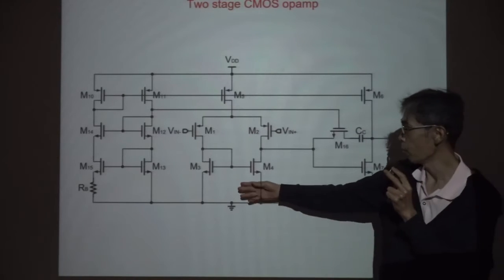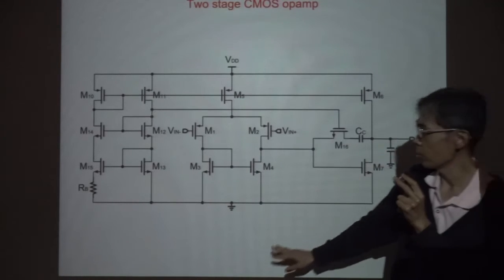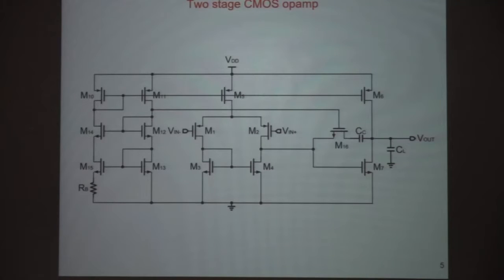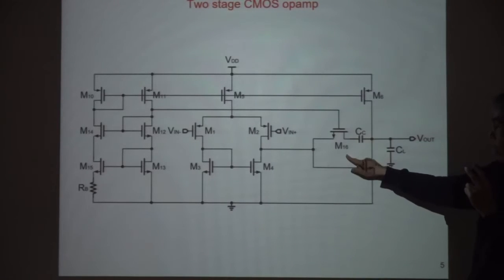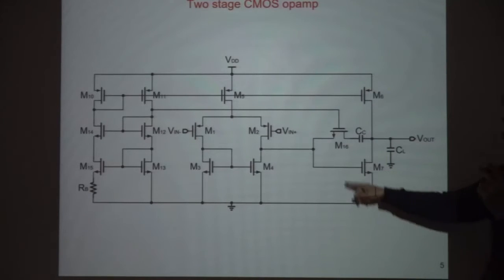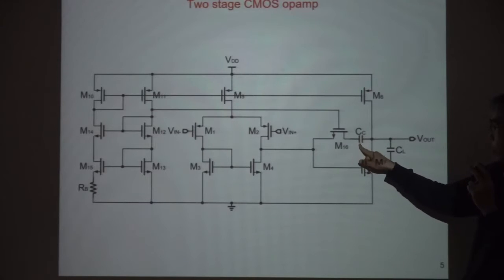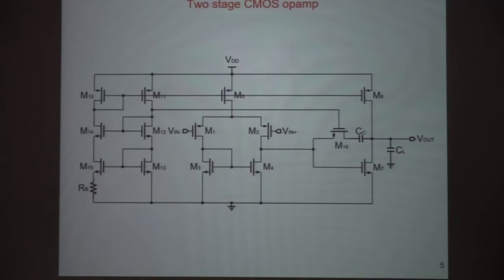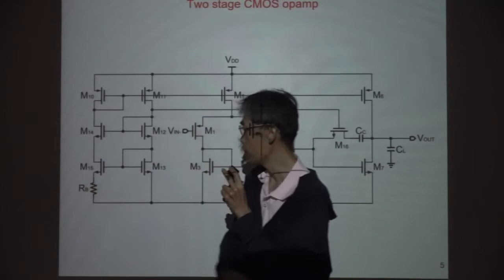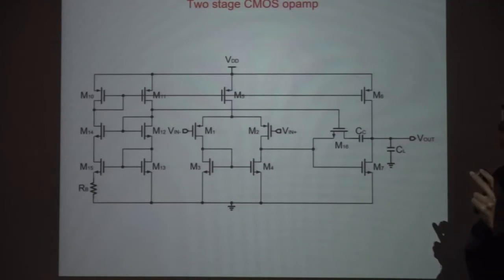Okay, so we have A1, A2, and this is the supply voltage. And this is RZ. We use the triode operation of a MOS for RZ, and this is CC, the compensation capacitance. And also RB, we need to decide RB to fulfill our requirement. Next.